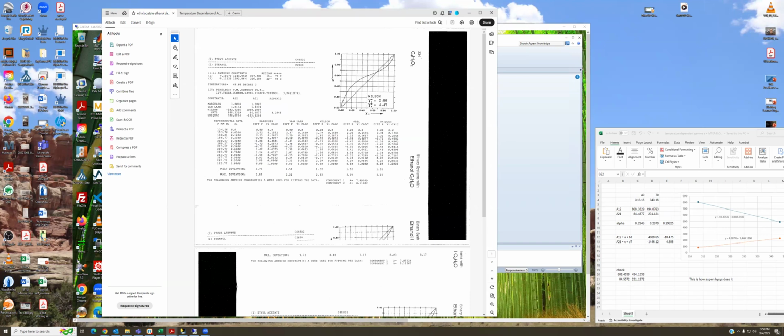Here you see a set of experimental data for this binary mixture measured at 40 degrees C by the authors you see here. These data were taken from the Dechema compilation. You can see at that temperature, the azeotropic composition is at a mole fraction of about 0.67 in ethyl acetate. And the maximum in pressure, the azeotropic pressure, is about 220 millimeters of mercury, or about 29 kilopascals.